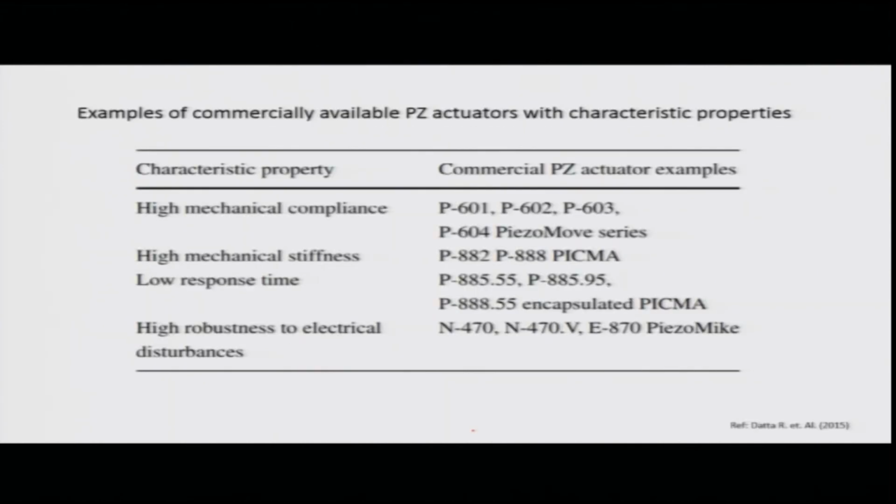So, you can make many such simulations of the system. Now, if you look at the commercial piezoelectric actuators, they actually exploit this. For example, high mechanical compliance: you would see this type of actuators available in the market. High mechanical stiffness: you will get this group of actuators. Low response times, which means the capacitors were in series, you will get this type of actuators. And high robustness to electrical disturbances, for which you need to have the capacitances in parallel, you will get this type of actuators.